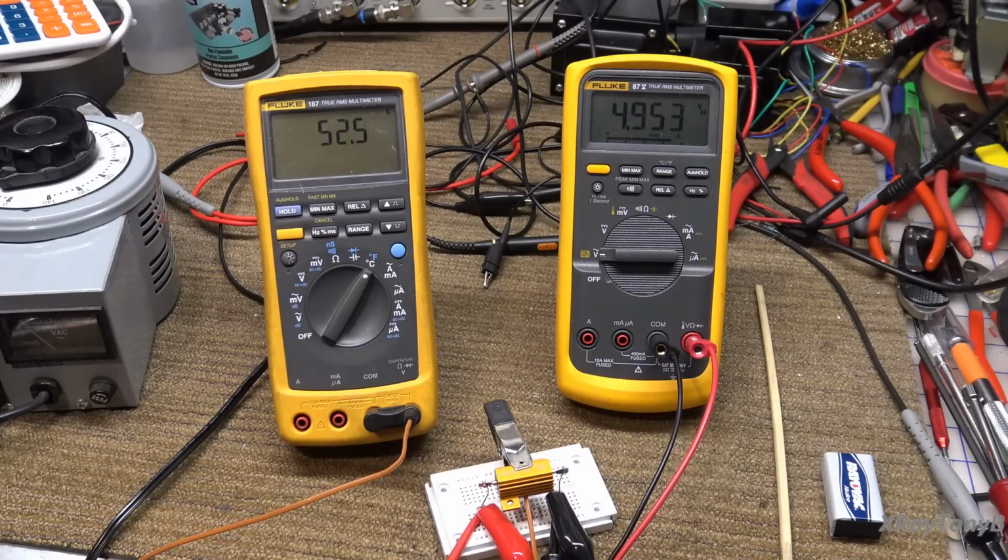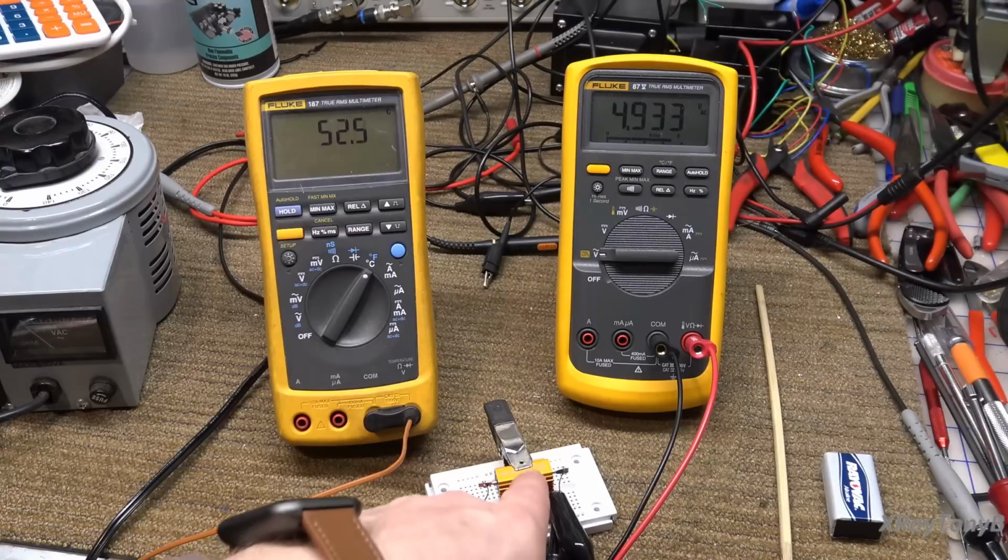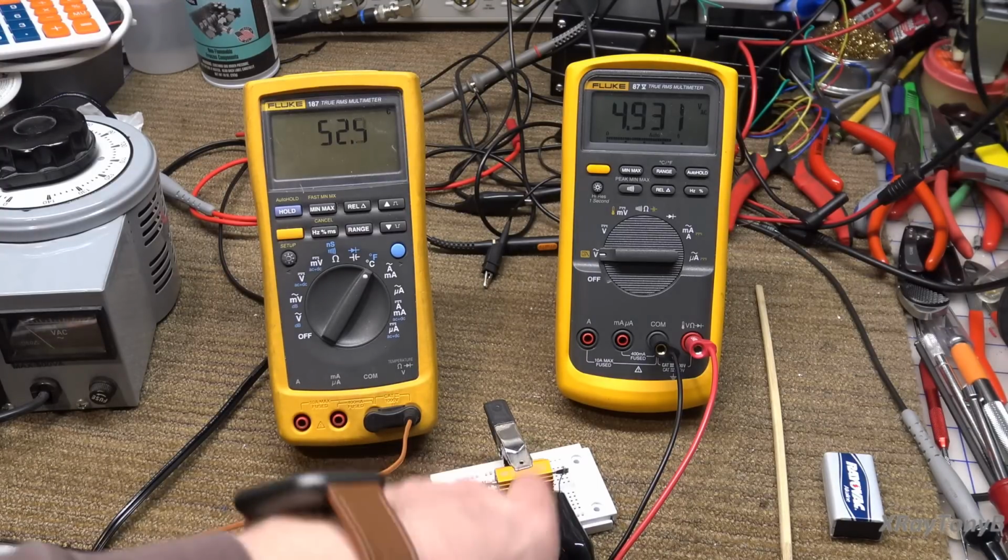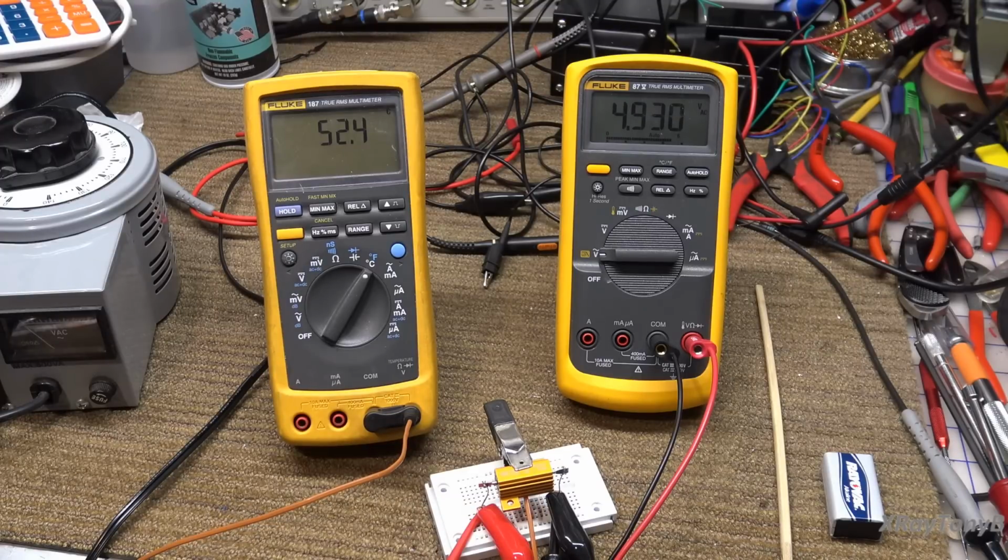So in other words, we need about 7 volts peak to get 5 volts RMS. What I'm driving at is the RMS of an AC signal is equal to an equal amount of DC voltage. So 5 volts RMS will do the same amount of work or create the same amount of heat in this resistor as 5 volts DC. Pretty cool, huh? And that's why we do that.